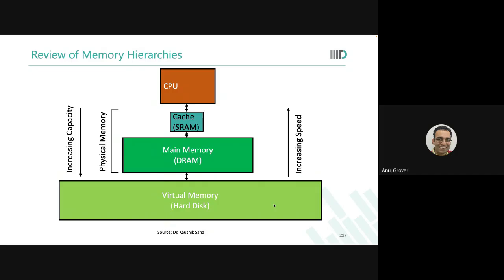Performance of memories has not scaled in line with logic. That is one aspect. Another aspect is that because of more integration, which again is an outcome of scaling, you now need larger memories. If you increase the size of on-chip memories, again, RCs will increase.